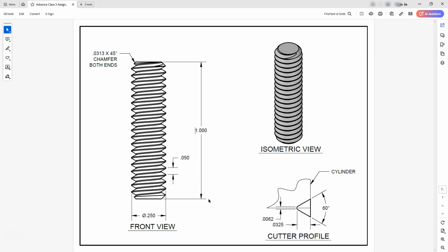Now remember that the Coil command is going to be in Inventor and it incorporates a Helix with it. Whereas if we do this in AutoCAD, we have to create the Helix command and then do the sweep. So Inventor does this a little bit quicker and easier for you.